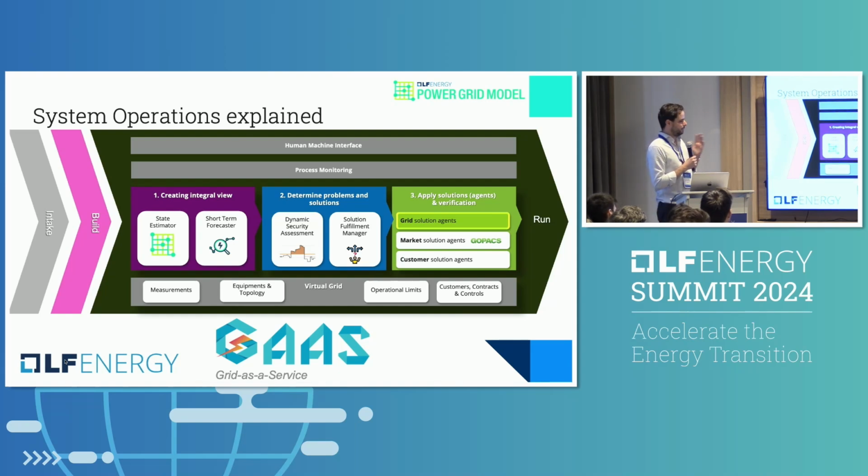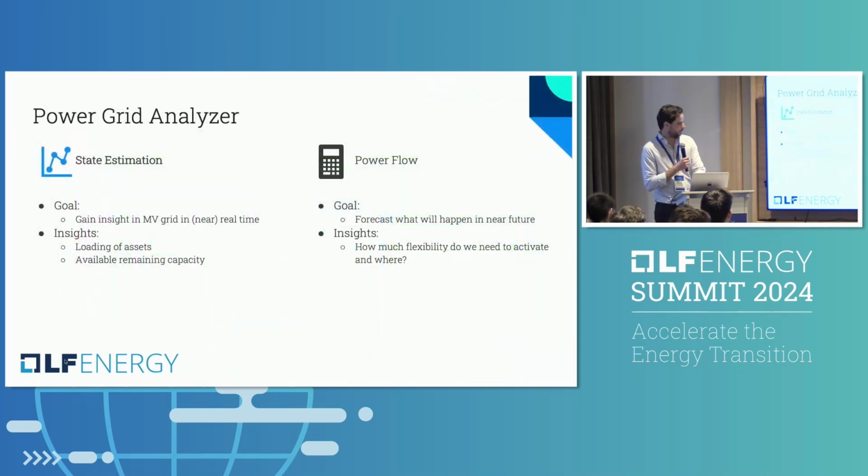And that's the Power Grid Analyzer. That's what we called it. So it can do 2 things. It has two of the functions from Power Grid Model that it can use, state estimation and power flow. And for state estimation, the goal is to gain insight in the medium voltage grid in near real time. So we gain insights in the loading of the assets and the available remaining capacity.